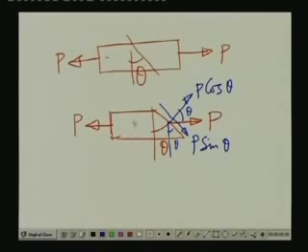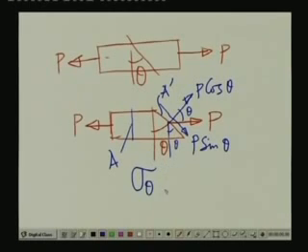Now, if we say that the cross sectional area here is A and the cross sectional area of this as A dashed, then the stress acting in this inclined plane, the normal stress sigma theta, theta being designated by this plane which is cut at an angle of theta with respect to the vertical, is sigma theta equals the normal force component, which is P cos theta, divided by this area A dashed.